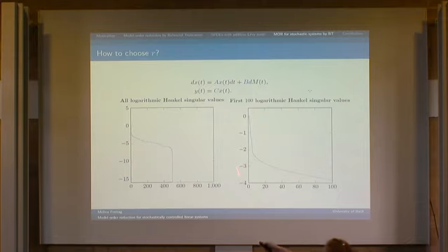This is zoomed in here. So look at the first 100 Hankel singular values. It kind of makes sense to cut off in around here. So 20 Hankel singular values seem to be enough to capture the dynamics of the system, because that's what it's all about. The dynamics of the system can basically be represented in a much smaller dimension.